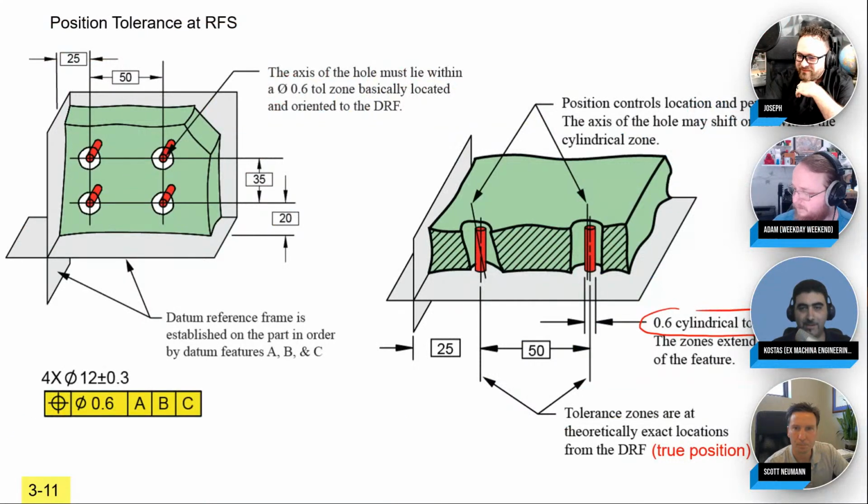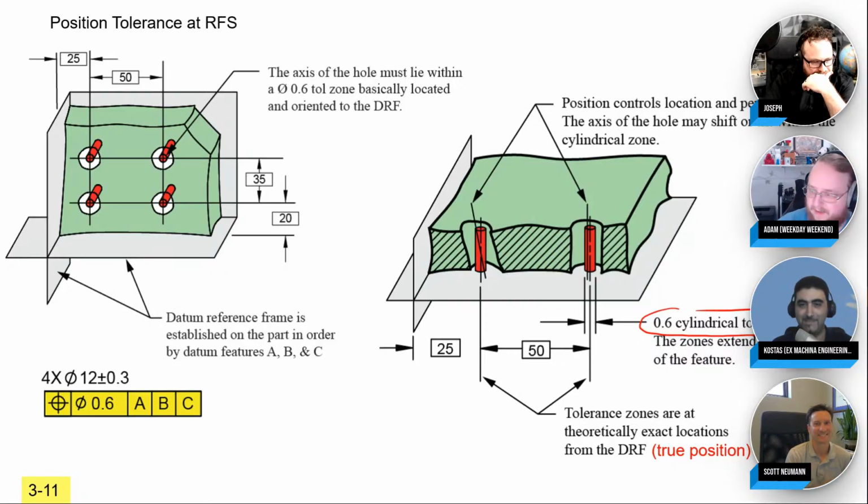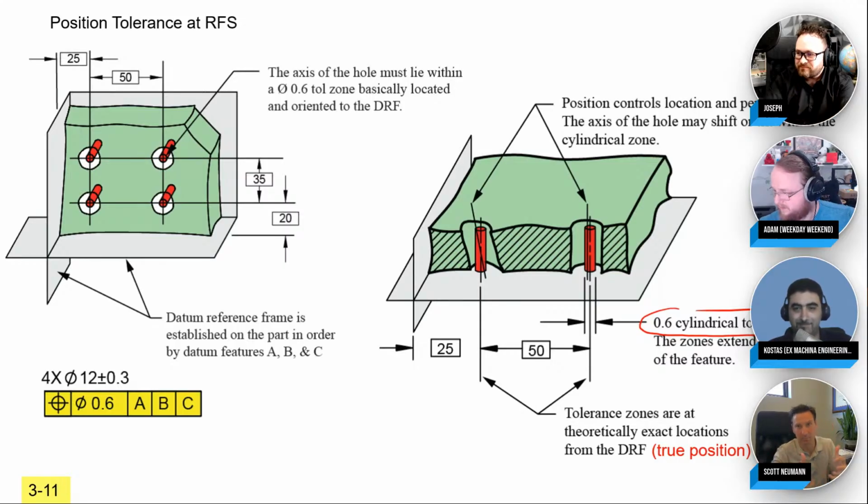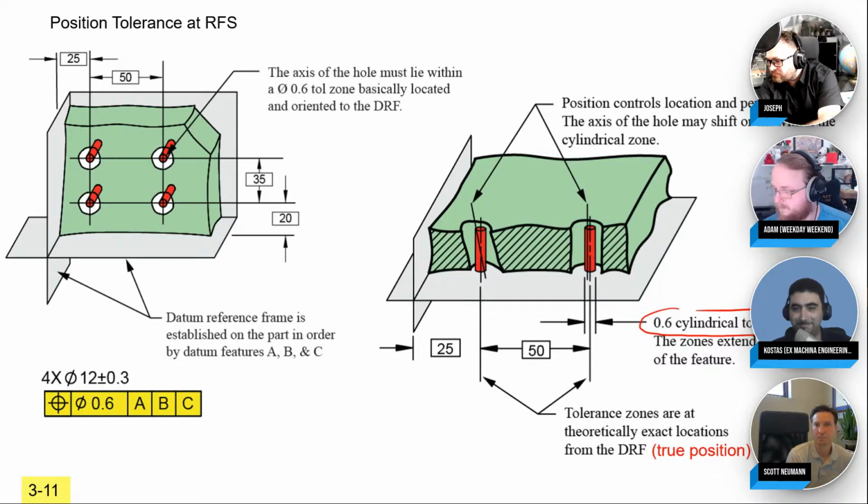Which, if I can just jump in for my fellow Libre users, it's like what we do when we're assembling a part. It's the exact same mindset, right? Yeah, when you first constrain the position of your first part. Very nice, what a good analogy. Yeah, how you align it in the assembly, bump it to this face and then down to this edge, or this shaft or this hole, or however it ends up meeting in the assembly. Yep, great comment.